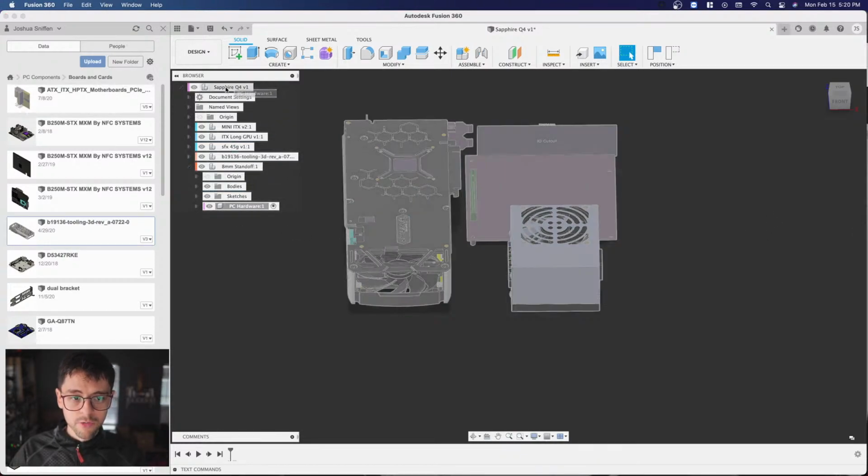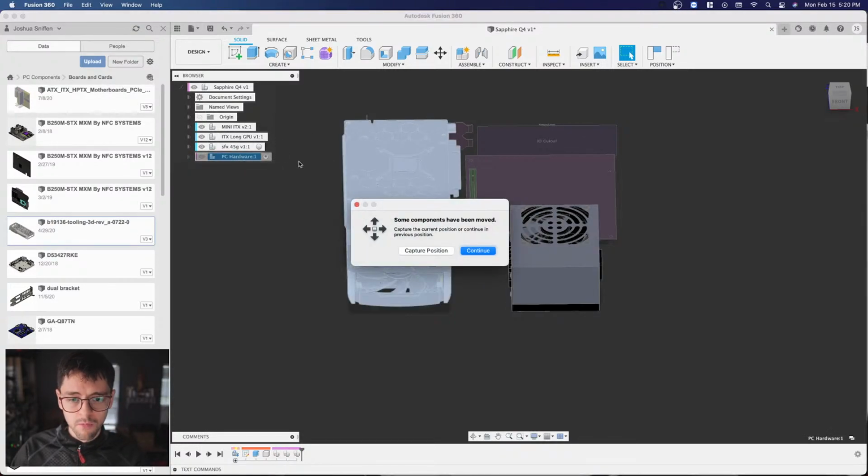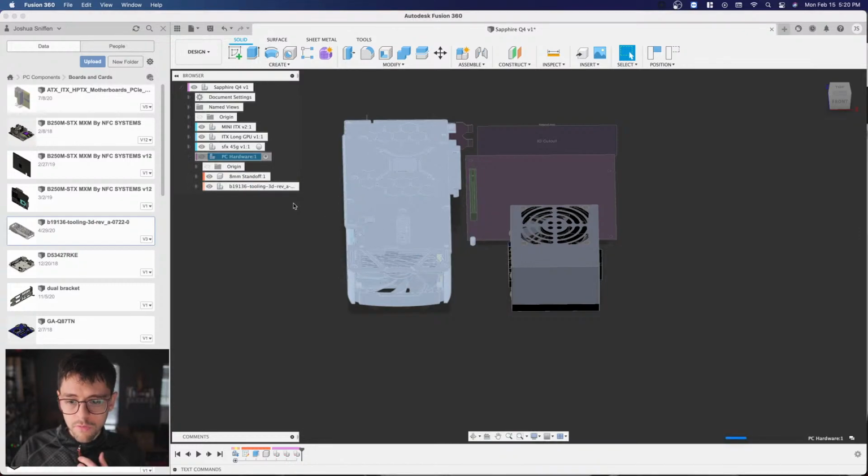Now, luckily, Fusion 360 allows you to move components around on your tree now, but when you first had to start working with Fusion 360, you couldn't do that. So they had this thing called, I forget what it was called. It was like the first rule. I think it was called rule number 1. That's what they called it. Really simple. And so if you're watching Fusion tutorials, you'll hear about that. That just means as soon as you open the document up, create a new component and then start modeling in it, because you couldn't move things out of your main component.